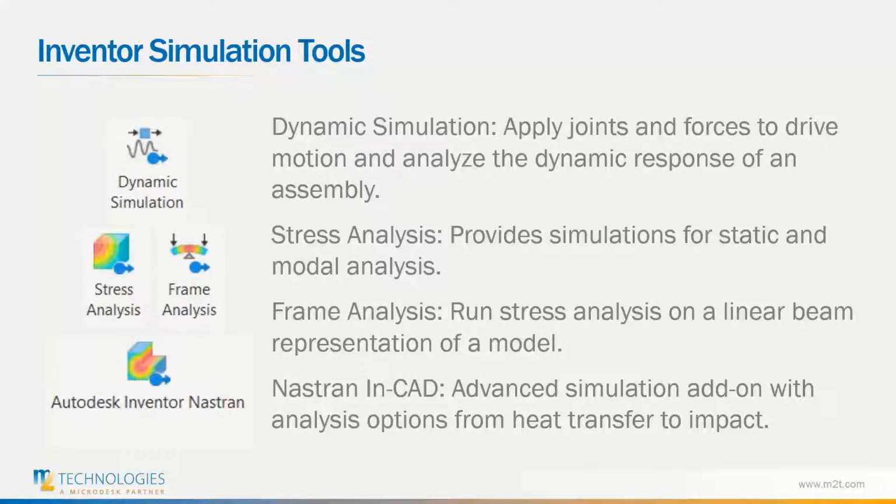There's then the stress analysis, which provides simulation for static and modal analyses on 3D objects. The frame analysis, which allows you to run these same studies, but on frame components which act as linear beams within the model. And then lastly, there's Nastran, which is an add-on to Inventor that comes with the product design and manufacturing collection.